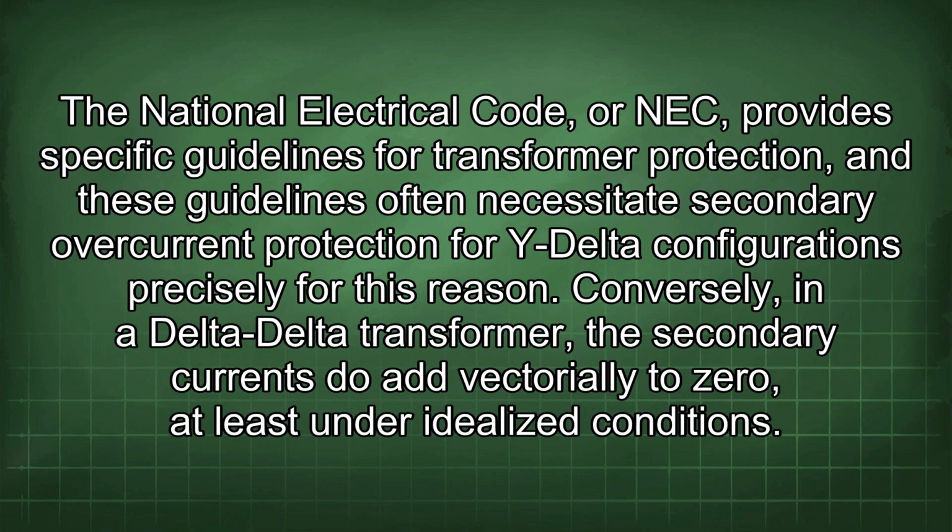The National Electrical Code, or NEC, provides specific guidelines for transformer protection, and these guidelines often necessitate secondary overcurrent protection for Y-delta configurations precisely for this reason.